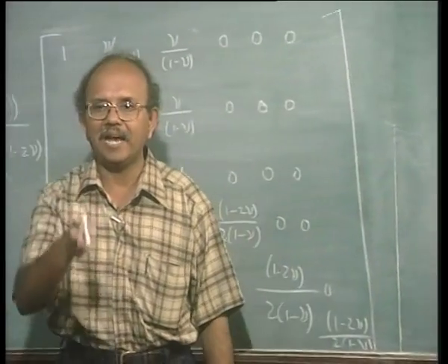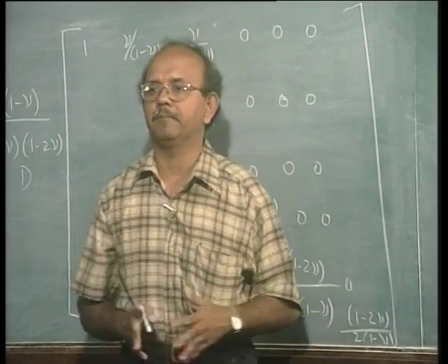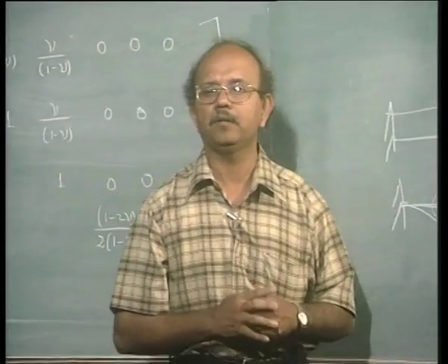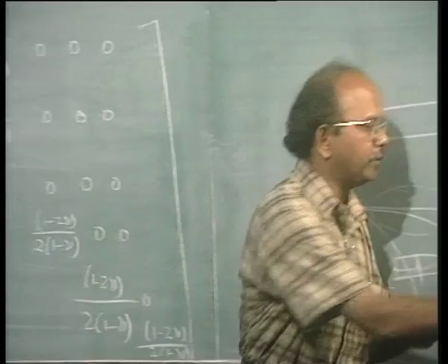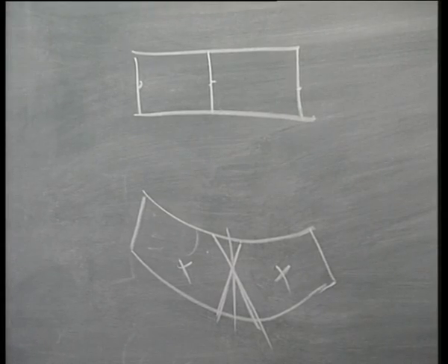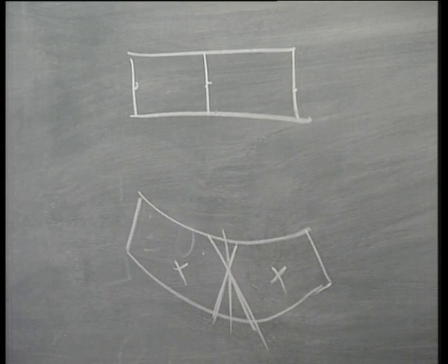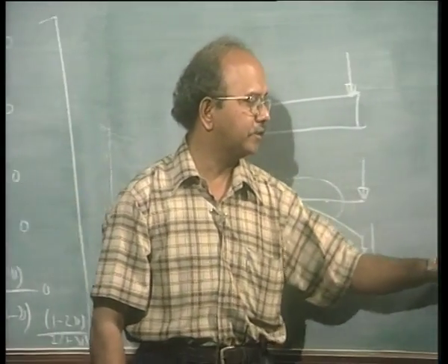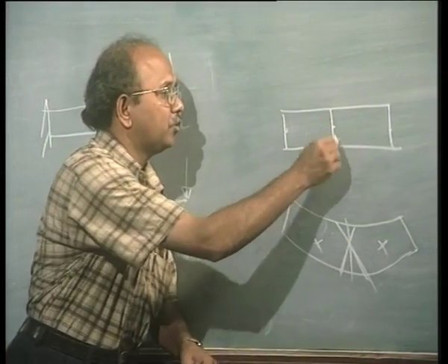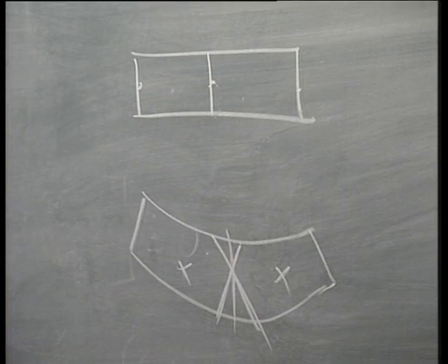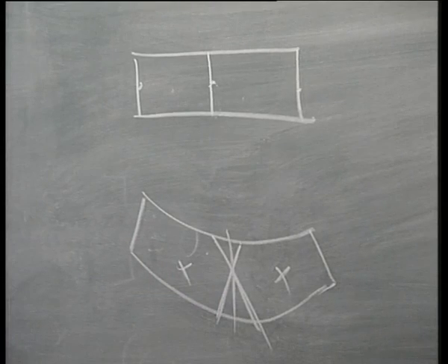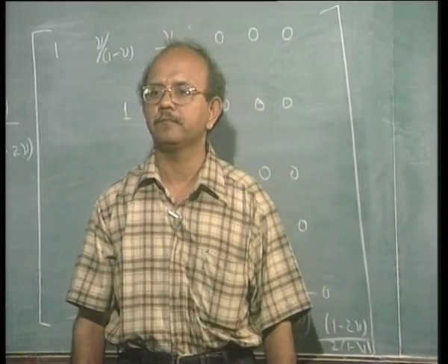In reality, what will happen to that line? It will remain the same, right. In other words, in order that the situation is compatible, that line has to appear to me as one line, and hence I have to specify theta as a degree of freedom, because in that case theta will be calculated for this node, and that theta will be the same for this element and this element, because that node is shared by these two elements. And hence from a compatibility point of view itself, from a very physical argument, it is very clear that theta should be a degree of freedom.